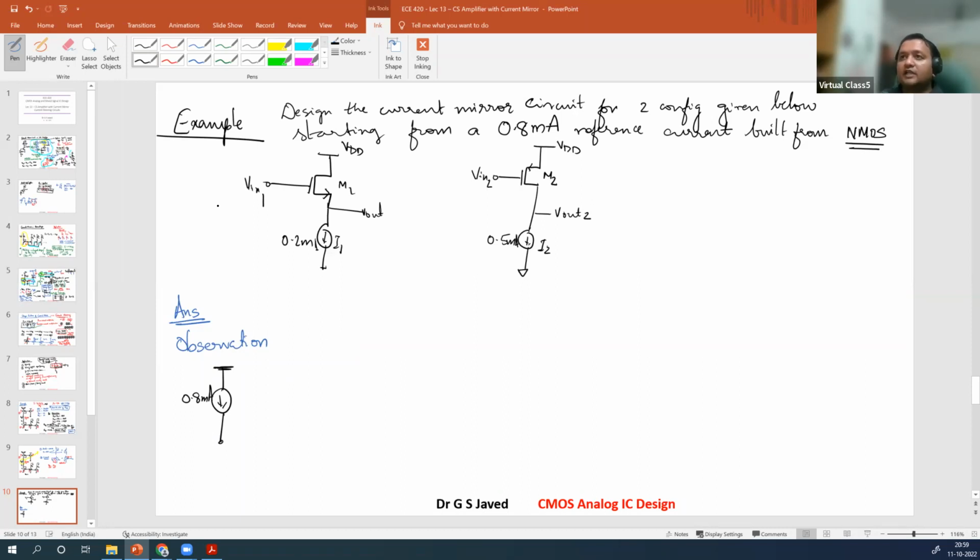First of all, understand you need to build a mirror circuit. So the moment you have this, the mirror circuit is your diode circuit. Right? So now you have done a current to voltage conversion. Now you will distribute this voltage. And what is this device? This is the VGS that is being applied. How do you need to distribute? You need to understand what is the load current. So what is the input current with respect to the output current?